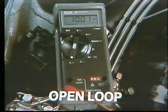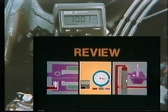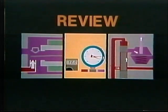In open loop, oxygen sensor disconnected, engine warm, actuator current should be about the middle of the fluctuations and as specified. When you see no change, you know the system is open loop. You may stop now for review of mixture control by actuator current.